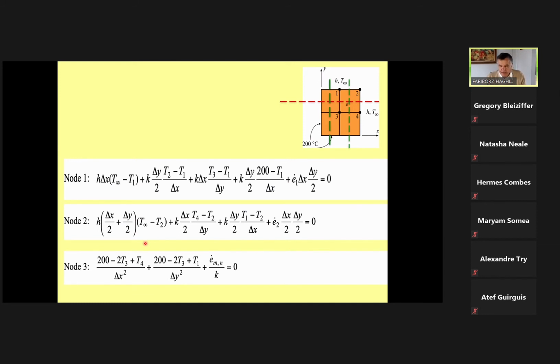Let's move. Therefore, as I mentioned, we are in chapter 7. In chapter 7, we are looking at convective heat transfer, forced convection over an exterior surface, okay, outside. We discussed in detail this scenario. For a flat plate, we have air or gas coming here, and slowly the velocity profile develops, and we have a boundary layer right here, okay? So this shows the velocity profile as it slowly improves, and here we call this the boundary layer.